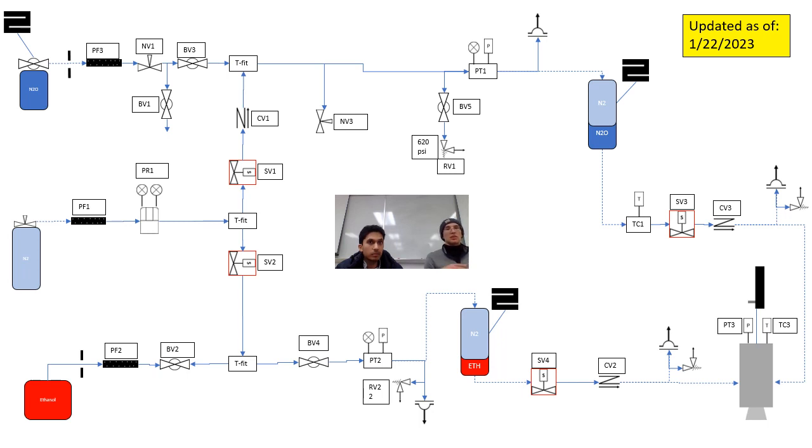When you set something to 15 psig, which is like 1 atmosphere above atmosphere, and you have a box that's at 15 psig and there's a little hole, there's a delta of about 1 atmosphere on each side of that hole. So that's just for the purging process. And that could be refined as well if we want a faster purge or a more aggressive purge.